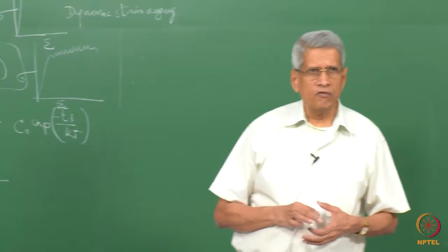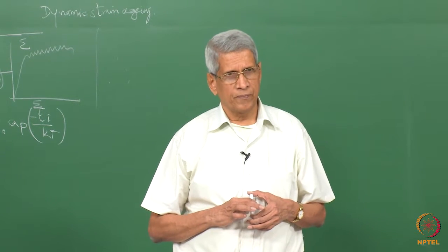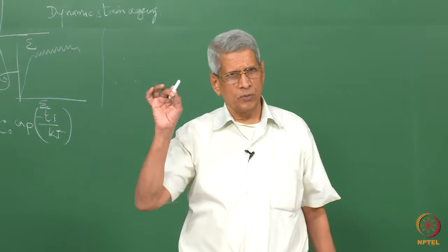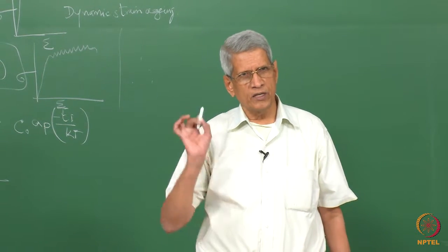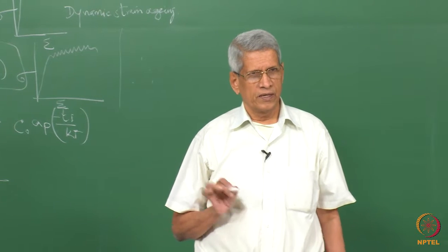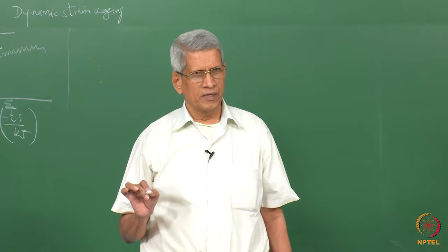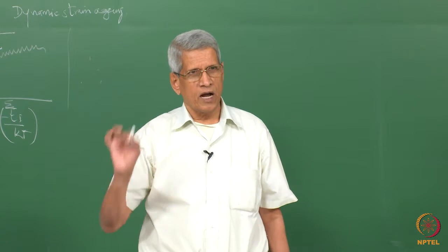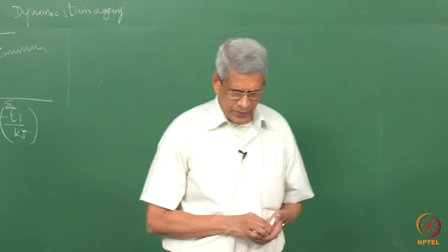In the case of a matrix, where the defects are distributed uniformly, the interaction is going to be essentially a diffuse type of interaction. With respect to a second phase particle, the interaction will be a short range interaction, when the dislocation comes very close to it, correct?